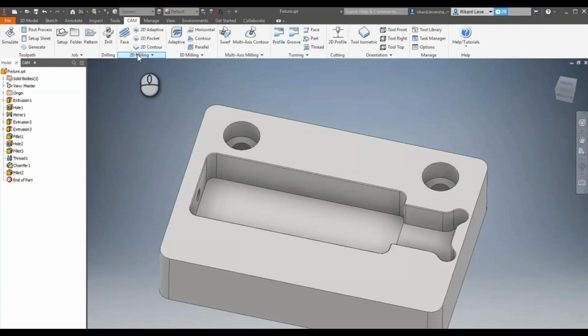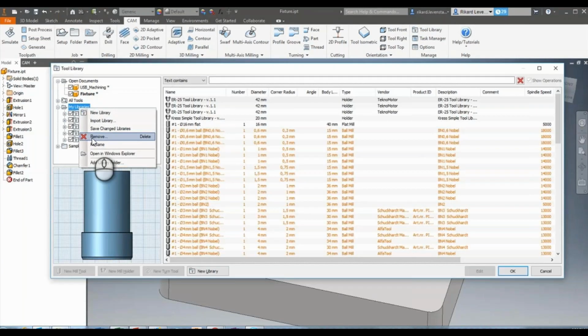Of course, at first, we jump into the CAM environment, and it's important for us to determine the orientation of the tool and how it's going to look. So the tool library. We're going to go into the tool library first. With HSM, you have access to creating your own library, removing libraries, or importing an already created library. We're going to create a new library quickly, and call it in there. If you go in, you can import a tool library from an existing library. So it's a .lib file, okay?